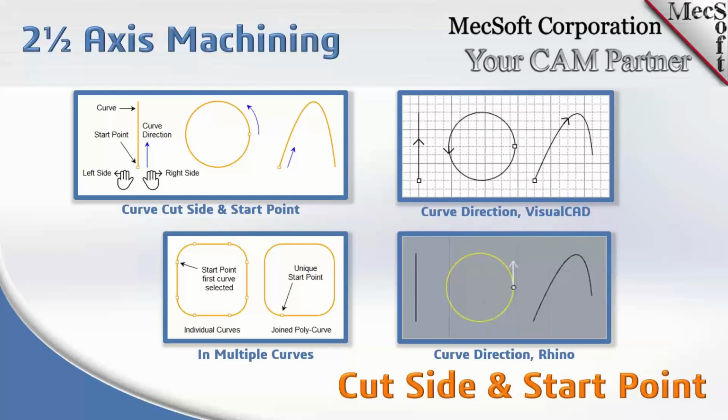If you look below that, you see examples using multiple curves. On the left, we have 1, 2, 3, 4, 5, 6, 7, 8 curves that are closed, but they're not merged into one single curve, so you see start points at each of the curves. We highly recommend that if you're going to machine more than one curve, you merge them into a single curve. On the right, you'll see the merged curve has one start point and is closed continuously.